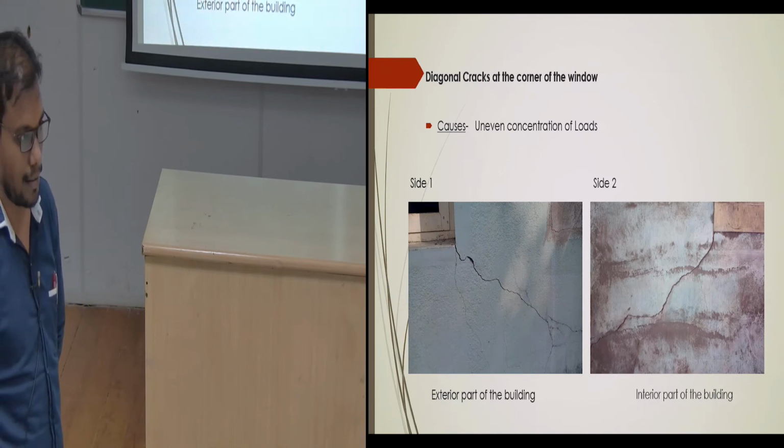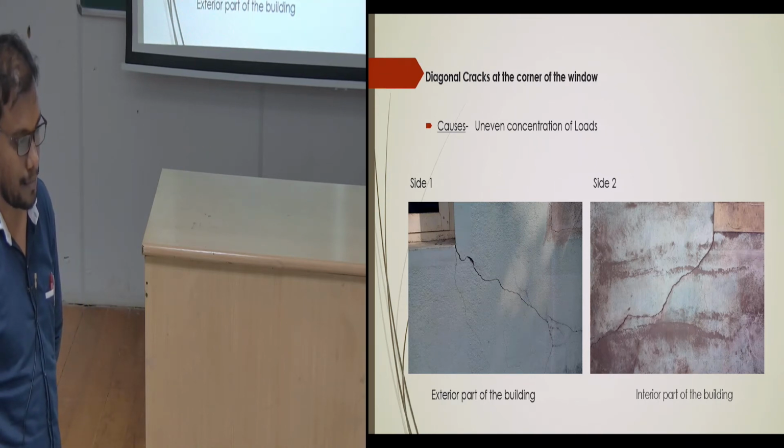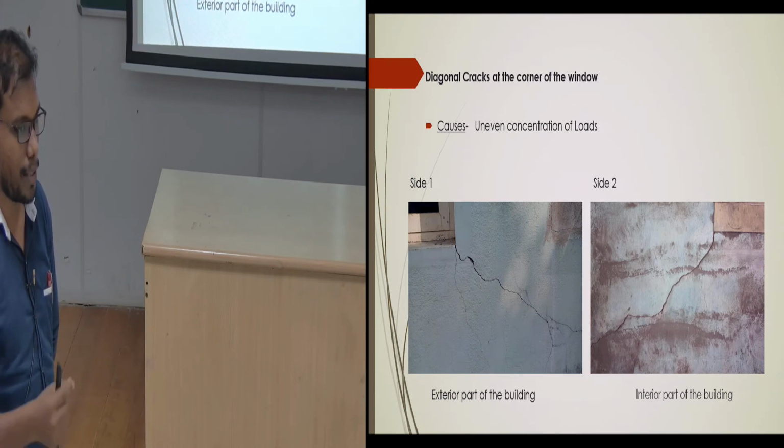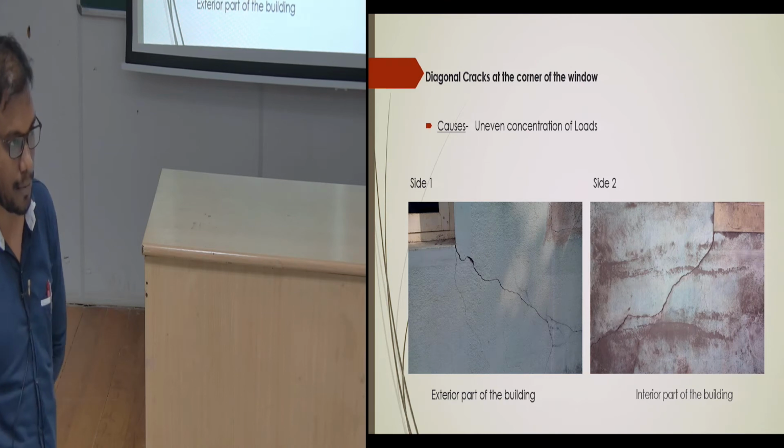You should give some minimal reinforcement at the base so that these diagonal cracks will be arrested. Nowadays a simple 6 mm or 4 mm reinforcement has been done. That is the correct solution.